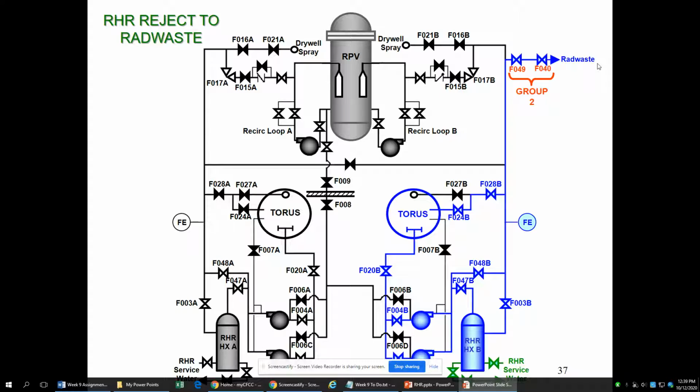We don't take in new water all the time. We will take in some, but we try to reprocess as much as we can, and we don't discharge any water if we can keep from it. It's very, very rare for us to discharge water, less than once a year for any large amount. So we reprocess it and push it back into the CST, and the CST eventually rotates it back into the reactor. And when it leaks again, or when the Torus fills up too much, we'll repeat the process again. We'll send it off to rad waste and clean it up.